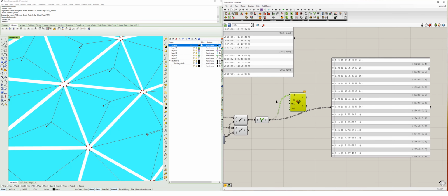And so that'll help when we type in for the offset, do quotes, open brackets, and then 0, semicolon, 0, semicolon, 0, semicolon, +1, closed brackets. And this is basically aligning to our branch structure. So we're not changing any of these ones, but we are working with the last branch. And that's why we branched it here, so that we can loop it in.